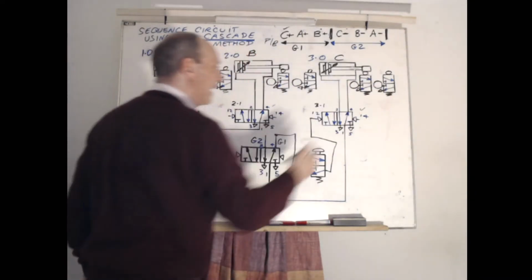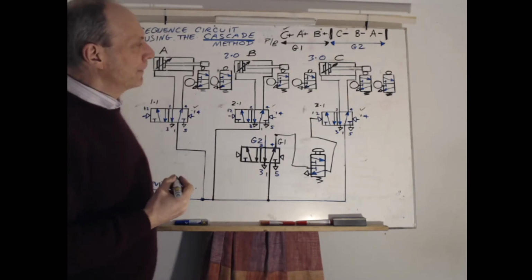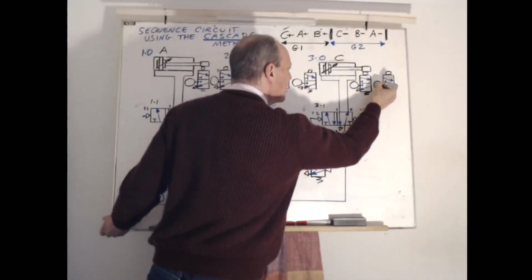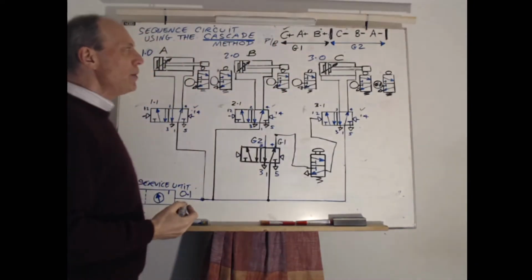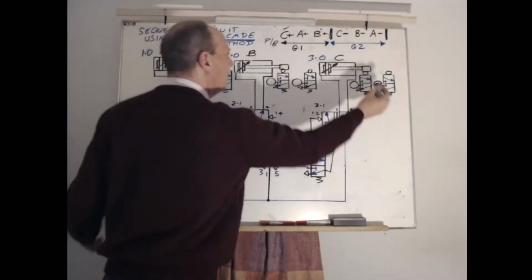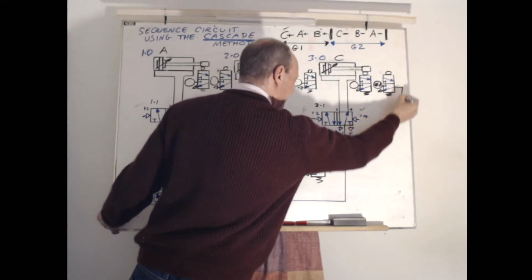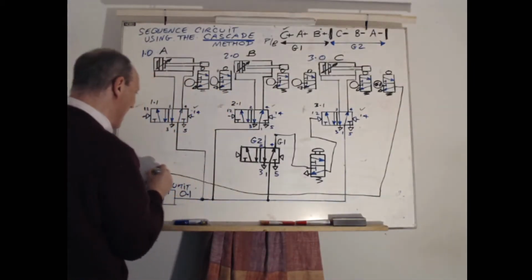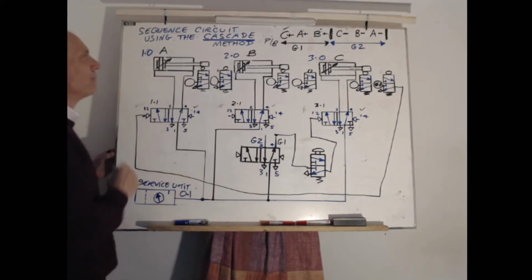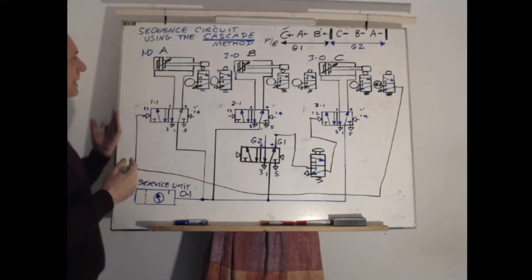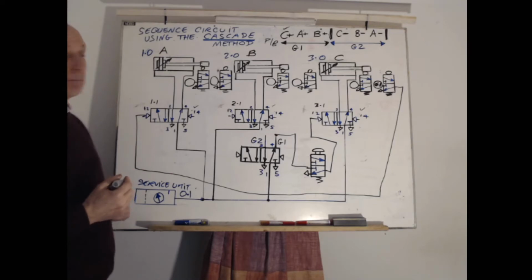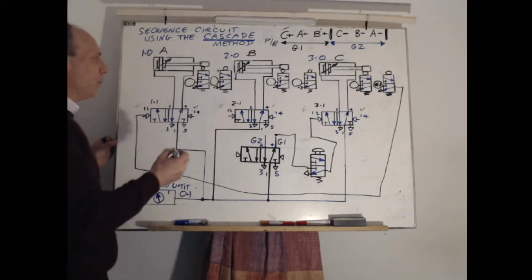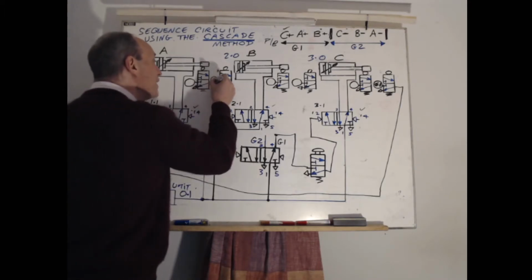It hits the valve on the outward stroke, the final position. So this must be G1A, because G1A is the air we're presently using. This signal is going to be taken and it's going to feed all of the way back, and it's going to operate A+. So A+ now goes forward. A goes forward and hits this signal valve on its forward stroke, which is also on G1A.